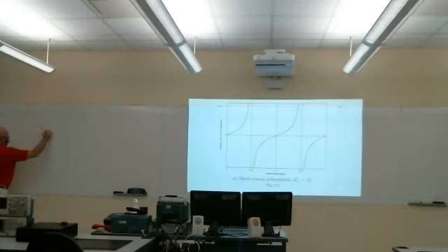So this is our load impedance, and we're considering the lossless line case still, where the alpha term is 0, or our propagation constant gamma is entirely imaginary, equal to j beta. We're considering a length of line L, but remember that we've defined z to be positive to our right, and we've put our origin now at the load.